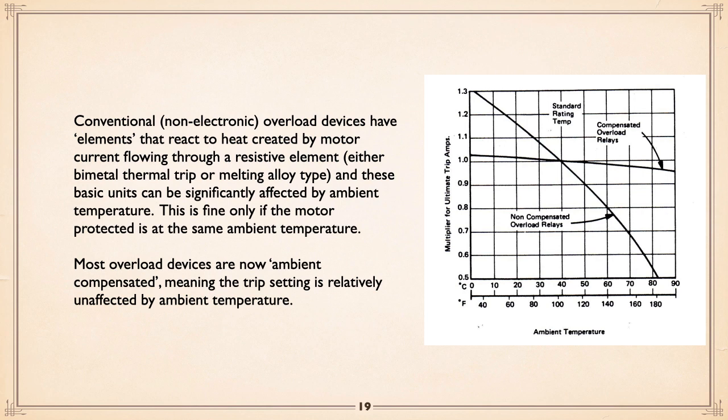Now, thermal compensated. What that means is, most overloads are thermal, though you're getting more and more solid state now. Classically, they had a bimetal trip element, and basically the current was run through a little heater. So the higher the current, the hotter it got, the quicker it tripped.